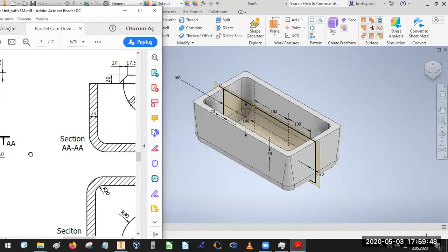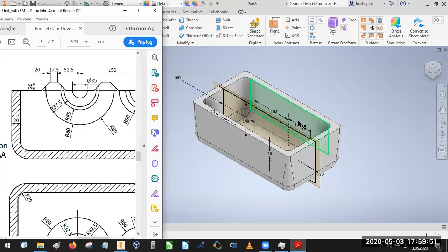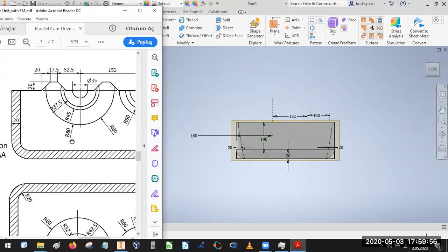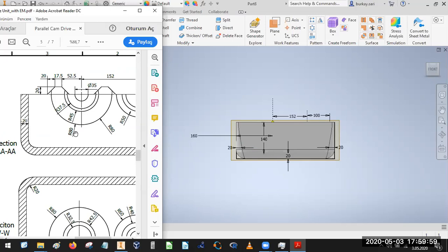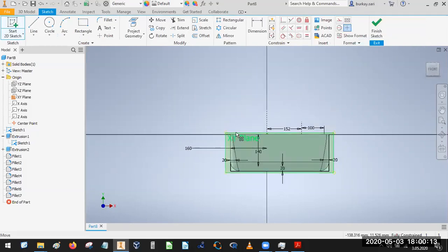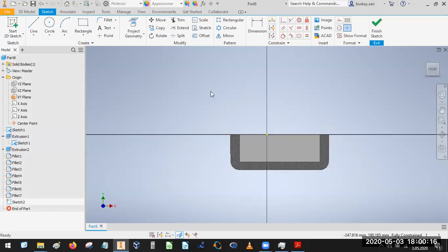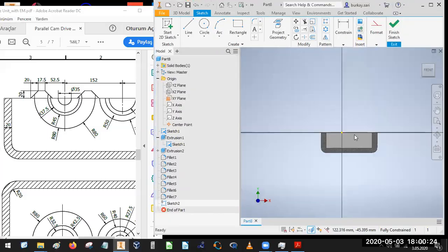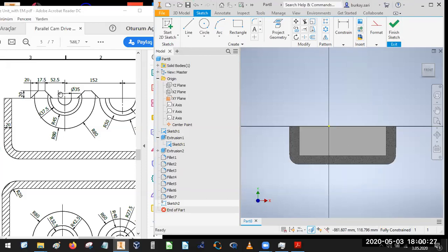And we will just create this sketch on the face, which we have seen from the AA sections, or this one. This is AA sections. Okay. For this, what I'm going to do is I will just create the face this time, and start a sketch on this face. With the F7 tool, I will just make a cut here. I have the origin point and just copy this sketch. And in copying, I will just draw this sketch. I will use these origin points.